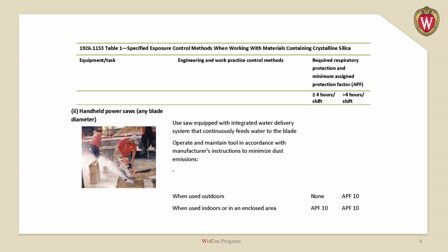You must ask yourself 2 questions to determine what, if any, respiratory protection is required for this task. 1. Will this activity take place outside or in an enclosed area? 2. Will the work take more or less than 4 hours to complete? The distinction between indoor and outdoor work is made because enclosed spaces reduce air circulation and can create much higher concentrations of dust.